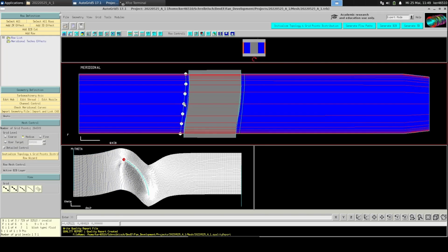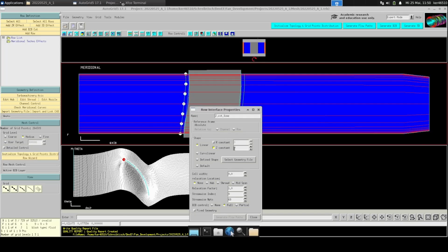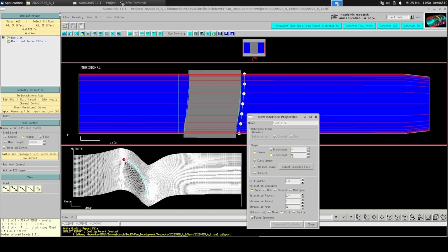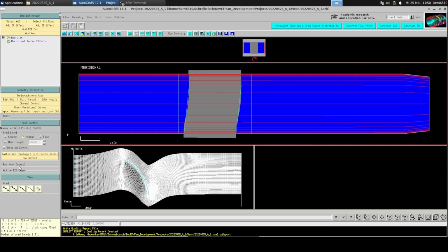If AutoGrid generates negative volumes, like in this case, go and see the Troubleshooting Measures section of the master's thesis. In this case, the set constant lines need to be reset to a linear shape at the location of ±3% on the relative fan axis. Also, a finer mesh can represent curved shapes better.